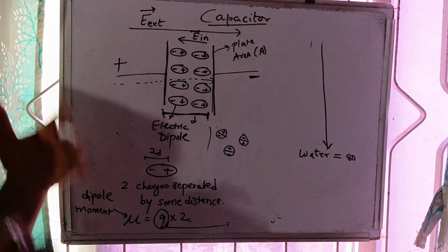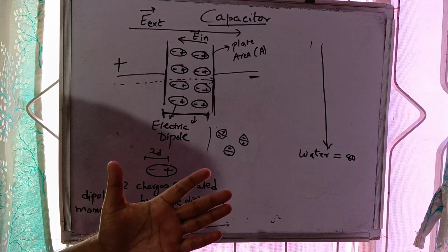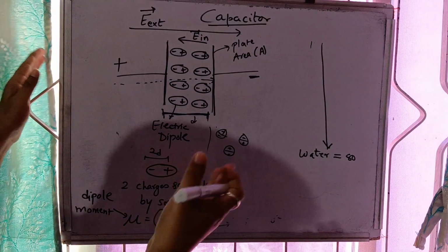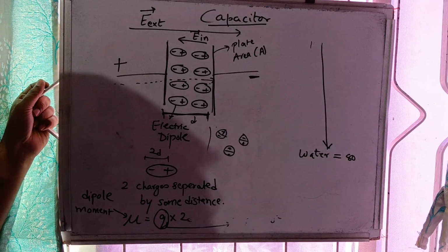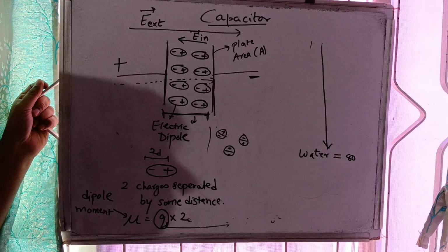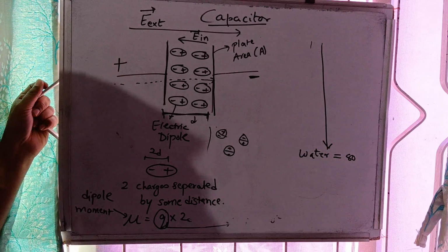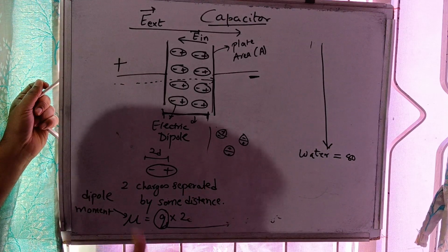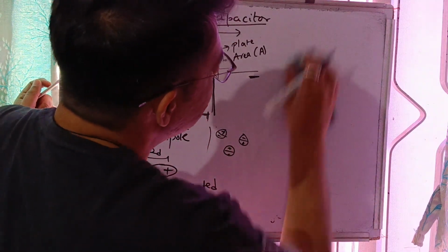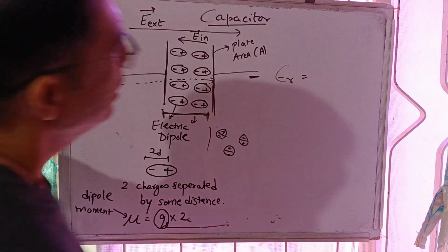But let us assume that it's a tank, and we are measuring the capacitance of the tank. In that case the capacitance will be higher. But if the water is empty, in that case air will be there within that, and then the capacitance will reduce. So it can be used for measuring the level also, depending upon the material being used within the particular vessel.